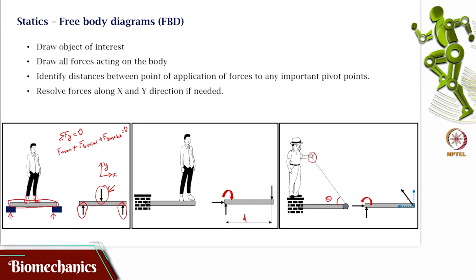So, it turns out that the force applied on that rope or cable is along the rope or the cable. Then this will be the free body diagram of this situation. There will be a force along the cable and the regular cantilever beam free body diagram, in other words two forces and one couple.